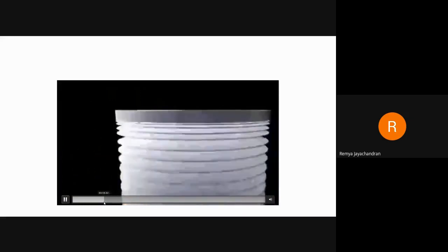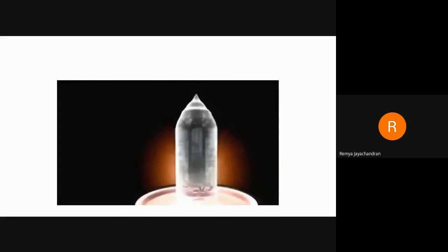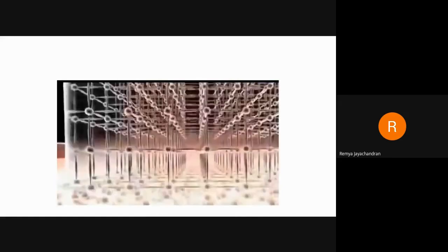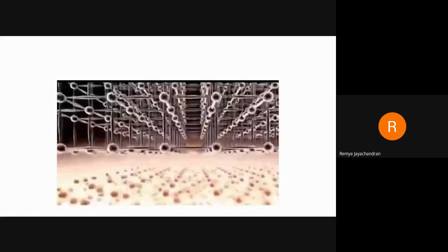Disk substrates for the microchips are made from quartz sand and are called silicon wafers. So these things you have seen in the previous video. From this sand, we are creating this high purity silicon. A huge monocrystal rod drawn from purified silicon melt. The result is a perfect silicon lattice into which the transistors will later be fitted.